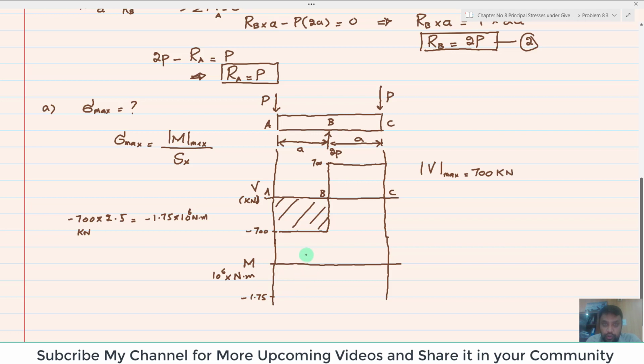Clear? So you can see at point B the area under this will be minus 1.75 into 10 raised to power 6. So at point B the moment will be this one. You can see this is a straight line, a 0-degree line, so the bending moment will be a linear line, and since it is negative, the slope will be downward. So this will be your bending moment between point A and B.